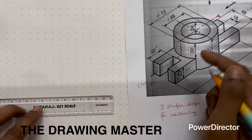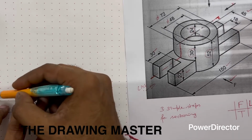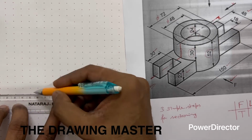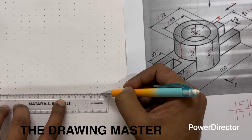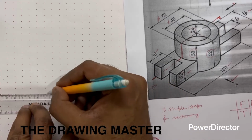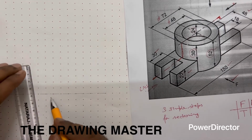So let's draw the center line first. This is 150. Here you have to keep a little bit of patience to draw the center line. Don't draw it casually. It's a chain type line. This is 150. You can also mark the midpoint. This is 70, 80 and in between 75. Here will be the center of the circle.